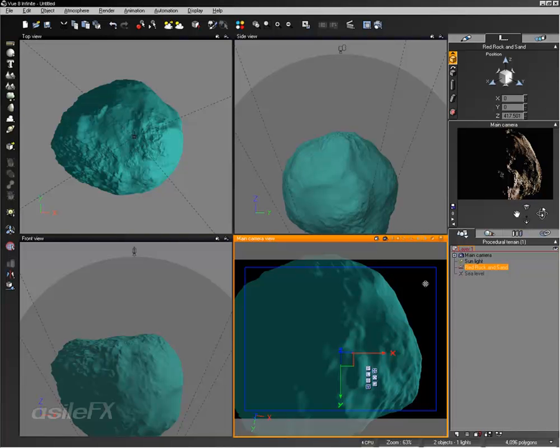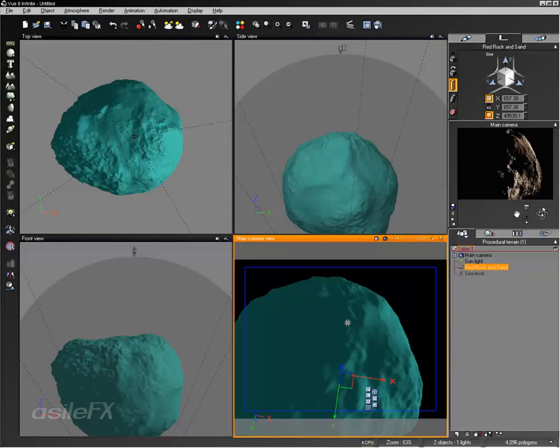Version 7, they made a lot of changes, but a view unit is the true unit of all objects, and it might give you a better idea of how to adjust scale. You can adjust the z-scale with these terrains, but it can cause some problems and sometimes resets them with the larger scenes. In this case, it'd be a little easier to modify it, but you can pay attention, and using a view unit sometimes gets a little closer to what you're looking for.